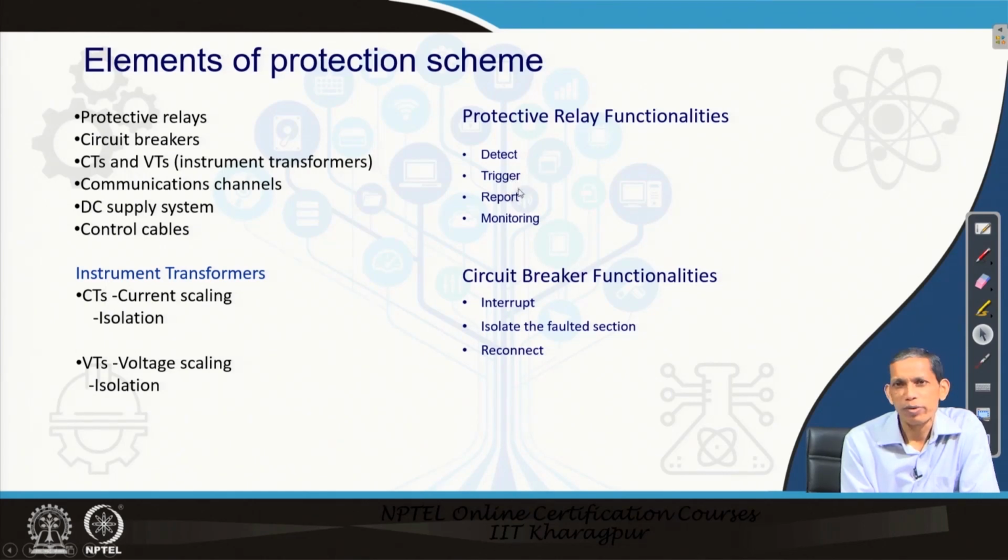It can store information on the fault, voltage, current, sampled sensor data, and it can produce a report which can be very useful for fault diagnosis and further analysis following a fault. It can continuously monitor voltage, current and other quantities, which can also be useful for metering purposes.